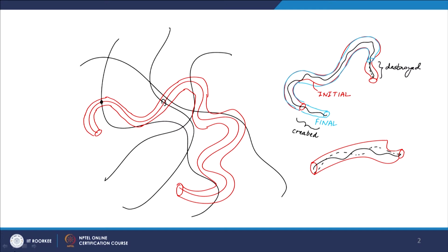The boundaries of the tube are dictated by the other polymer chains around it. As long as small changes in conformation do not affect the position of other polymer chains in the system, those small changes are allowed. So, as long as they are wiggling within the tube, the other polymer chains are not being affected, and that sort of wiggling is of course allowed.